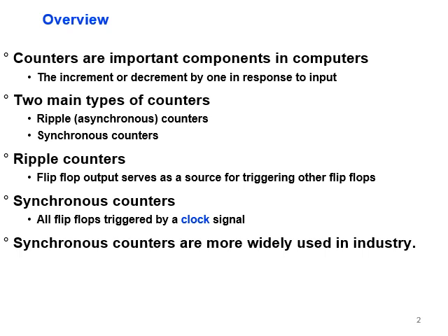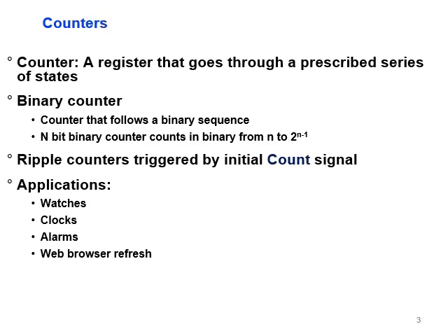In simple words, in the synchronous counter, the flip-flops will work together at the same time, simultaneously, based on the clock coming to all of these flip-flops. While in the ripple or asynchronous counter, the output of the first flip-flop becomes the input to the second flip-flop, and the output of the second flip-flop becomes the input to the third flip-flop, and so on. So it is not working together. There is delay all the time. We need to consider that synchronous counters are more widely used in industry and in applications. So it is the main type of counter available today in our technology.